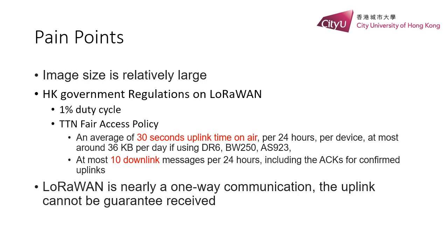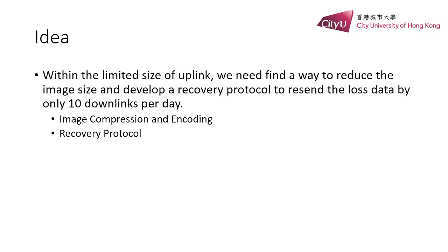Only 36 kilobytes data can be sent per day, and only 10 downlinks can be sent per day. This means not every uplink can be guaranteed to receive at server, because we cannot give every packet an acknowledgement. Our idea is to use the limited resources to send image for monitoring and make image can be resent when packet lost. So we need to develop an image compression and encoding algorithm and recovery protocols suitable for LoRaWAN.